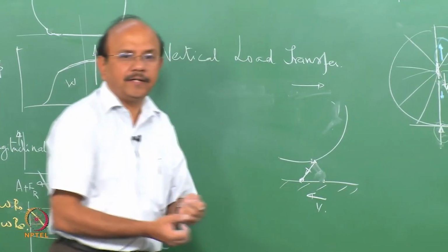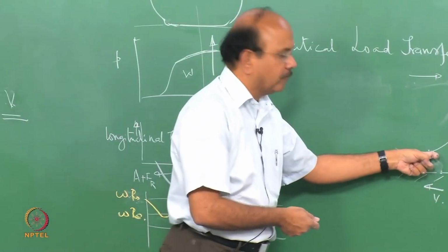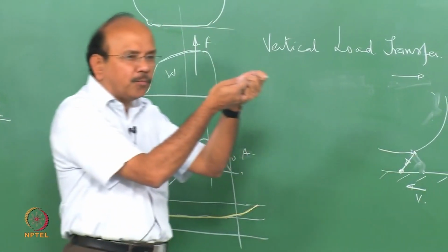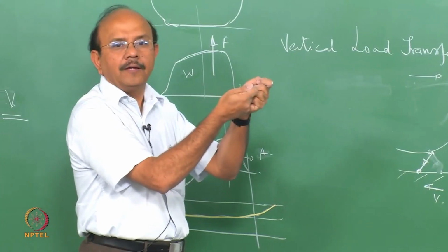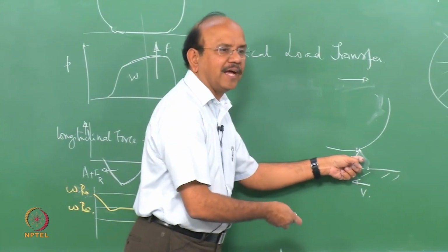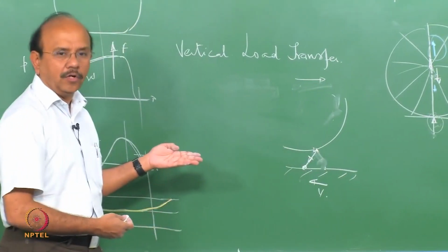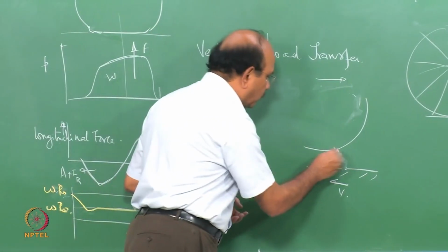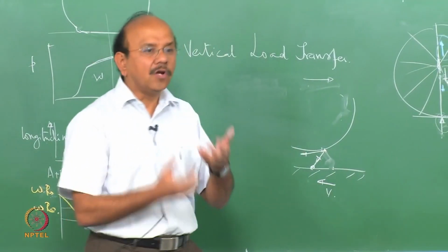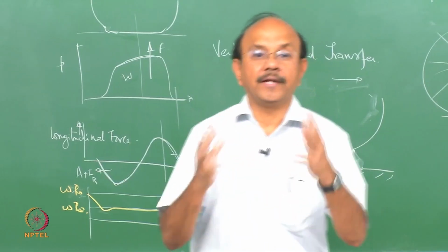So what will happen to the tread? He will now pull, he is not going to leave the other side. He is now going to pull the tire. Don't go away, I am being pulled here, I am going to stop you. If you now resolve this force in the longitudinal direction, that would result in a longitudinal force, and that gets depicted as a braking force.